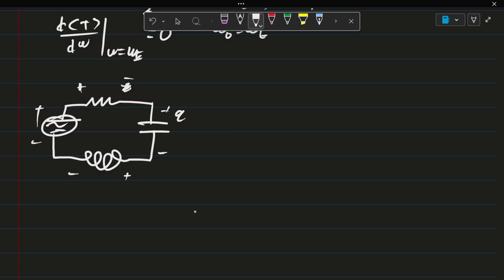So doing Kirchhoff's law straight away, you could get I times R plus the voltage between these two, which is Q over C, plus the voltage between there, it's L di over dt, must equal the voltage source here. And that's basically Kirchhoff's law straight away.